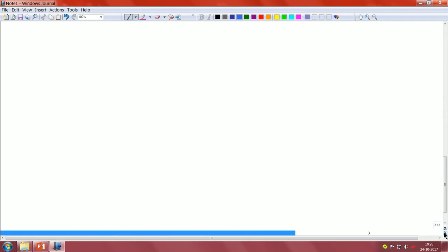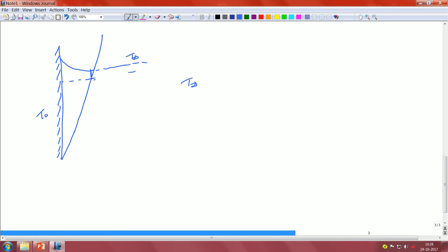So here, for example, this is the wall. It has a temperature T naught, and this is the temperature T infinity. I am assuming that the temperature boundary layer is moving up like this. Forget about my drawing, it is not wiggly, it is just a monotonous increase. We already said that this is the temperature, and it should come down and become the same as the ambient. This part I think everybody would agree, but the velocity is a little bit more dicey than that.